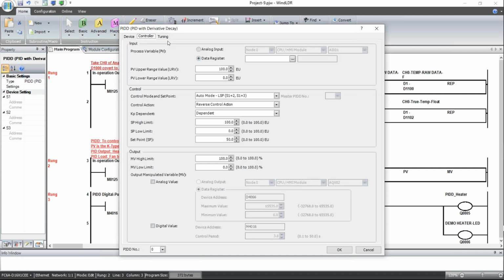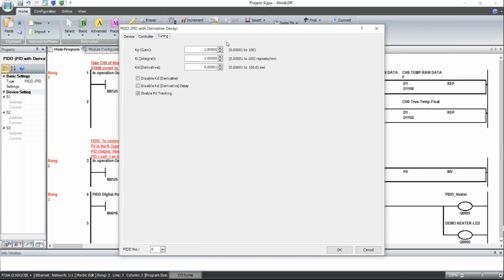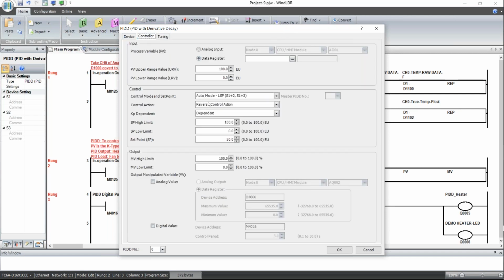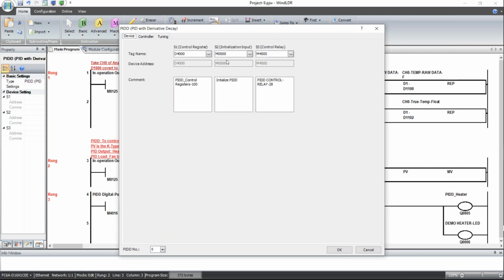So sometimes people want to revert to the original setting, and they may have to do that. That's the difference I'm showing you. For the sake of time, I want to put in automatic. I don't want to do it manually. I want to automatically initialize my PID.